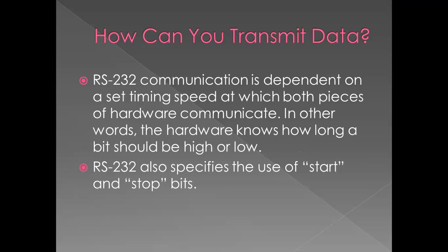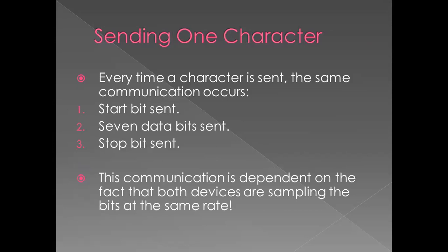How can you transmit the data? RS-232 communication depends on a set timing speed at which both pieces of hardware communicate. In other words, the hardware knows how long a bit should be high or low. RS-232 also specifies the use of a start and a stop bit when sending one character.